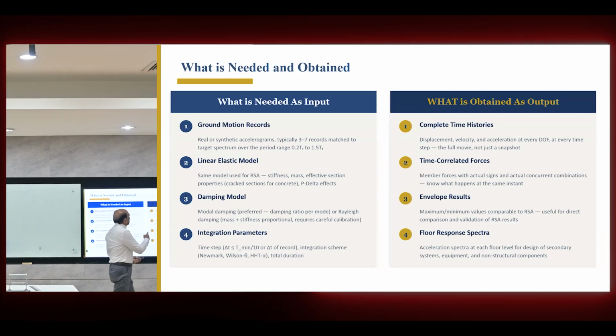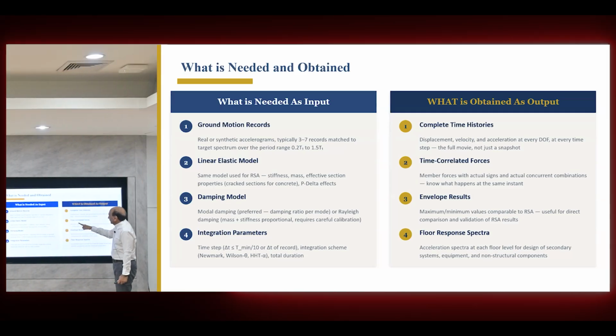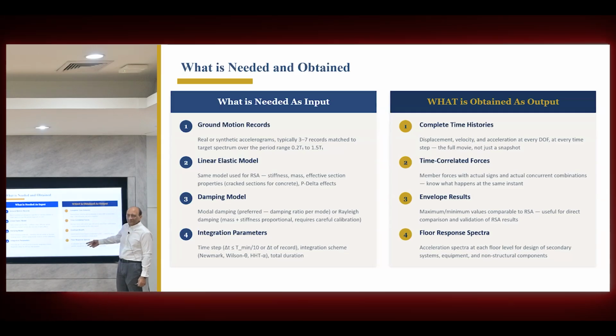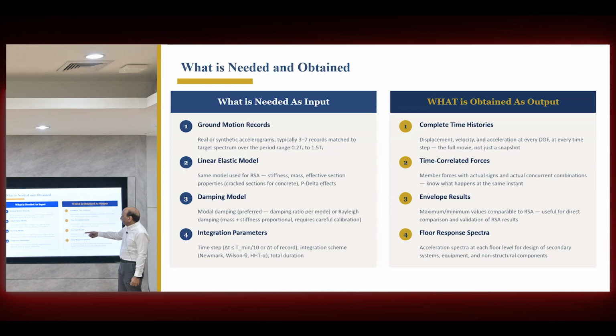So we get complete time history, time correlated factors, envelope results, and floor response spectra. Very important. You get every floor response spectra, acceleration, velocities, displacement at each floor, at each point actually. And then you also get envelope results.